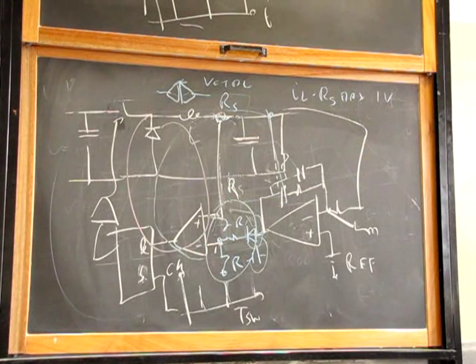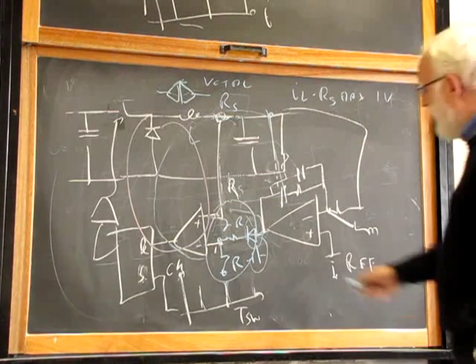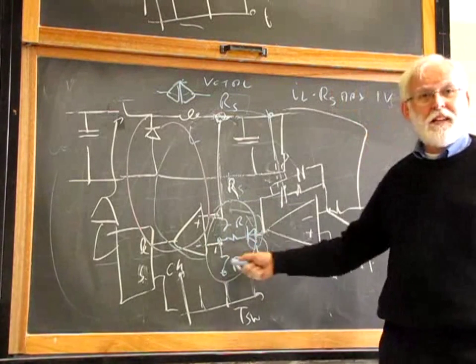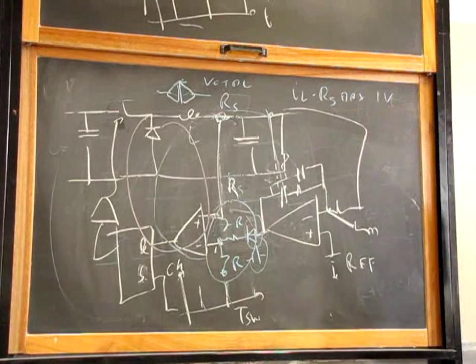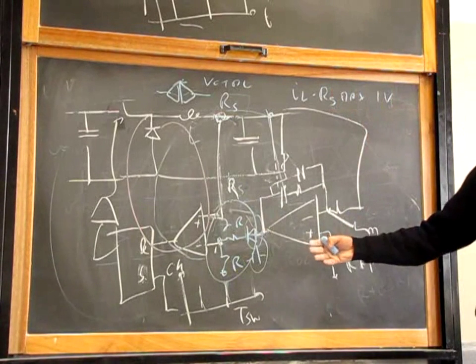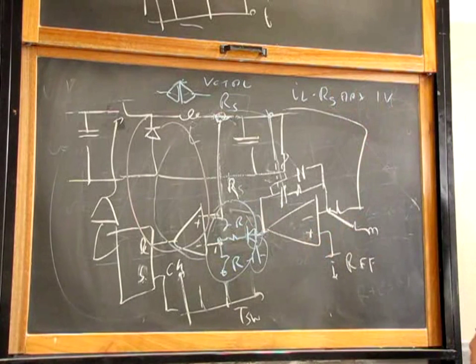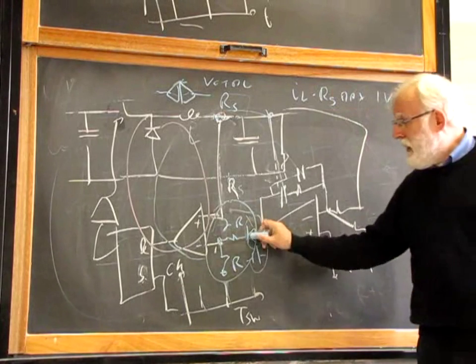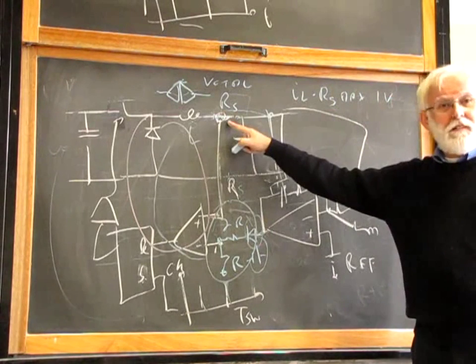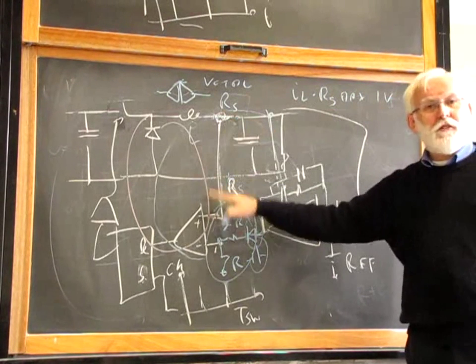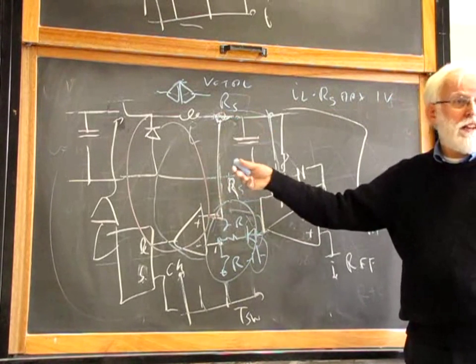So when we do the calculation of the loop gain, if we consider this, we have to remember that we have one extra 10 dBs lost over here, a factor of 3 lost over here. This is just a practical factor. There is nothing theoretical over here. In some other cases, for more modern integrated circuits, you have a direct connection, and between the sensing resistor input and the comparator, you have an amplifier by a factor of 3, so it's the same story.